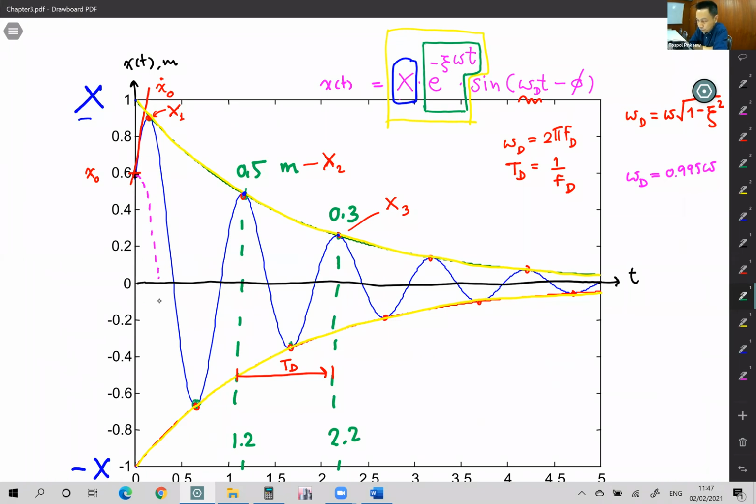If my building's stiffness and the mass are fixed, omega is fixed too, because omega is the square root of K over M. Therefore, what I have to do is to play around with psi. I have to find a way to increase psi of my building. Unfortunately, we have a fixed number for our structure, our building.